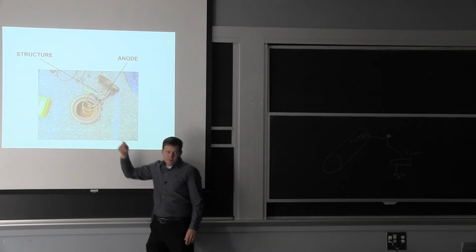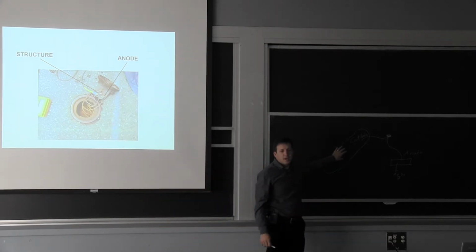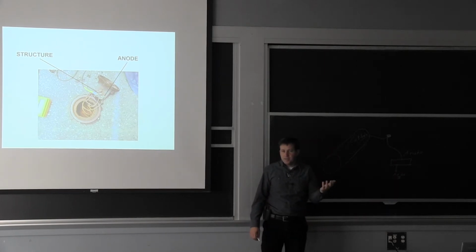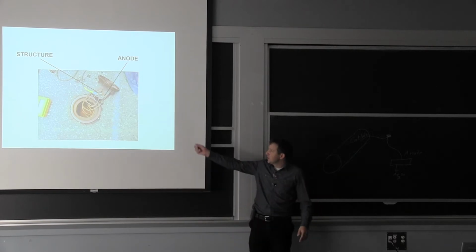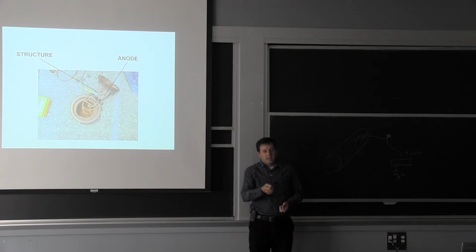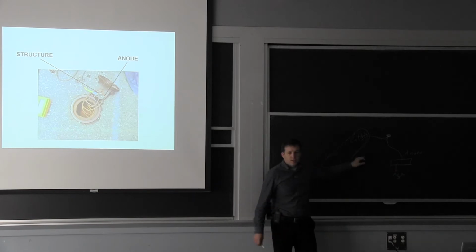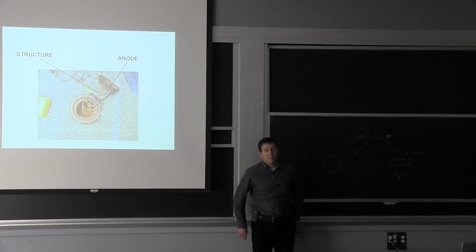A bunch of bond wires connecting to different sections of the pipes that you connect over here to different anodes in the ground. And what happens, say, 5 years down the road is you just go and open that little cover and you can test for the potential of the anode, and it's going to tell you whether you consumed it or not. And you can check also for the resistivity between the anode and the tank. So a lot of that testing, you don't have to go back and go underground. You really want to have an access point to do that.